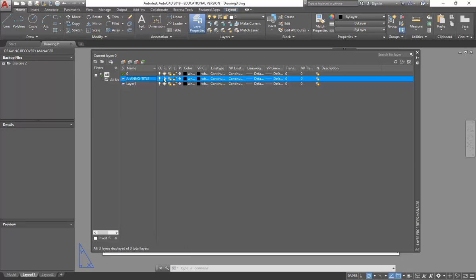So now, for colours. I'm not fanatical about colours, except that you use colours that make sense for you, not the things out of the list that you might have been given before. That's a really old thing, those standard colours. Do you know why they had standard colours? It was because the colours used to represent a line weight. So if you made a layer red, that would always print, say, 0.35, or whatever red was.